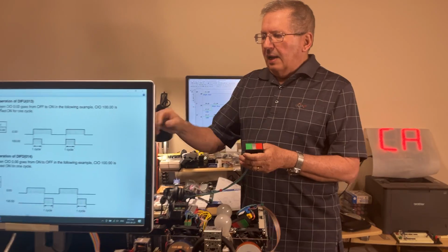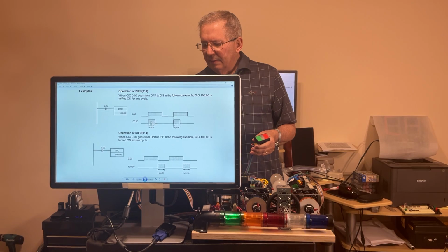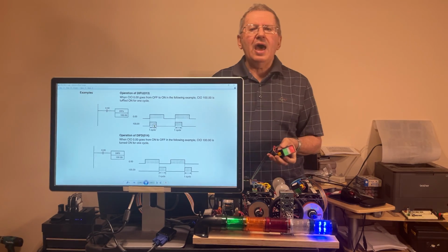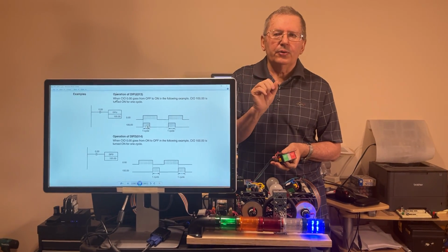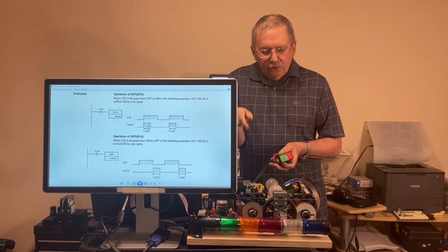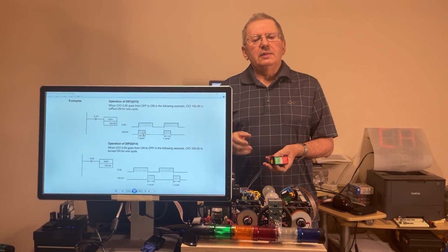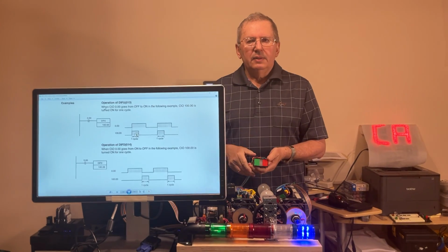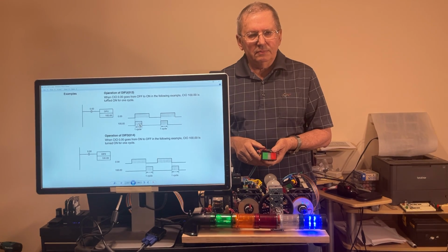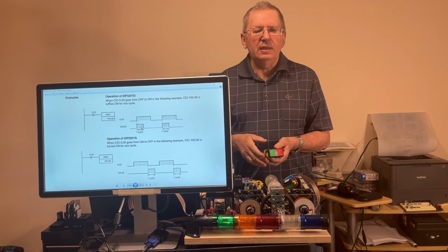It determines, exactly like you can see on the screen, a monostable, regardless of the duration I hold my finger on it. But this time I don't have direct control over the duration itself, because that particular instruction is related to the duration of an executing cycle for my PLC. As the executing cycle for my PLC is very short, the instructions are executed one by one, let's say in tens of microseconds. It doesn't take long. So the whole program, because it's a short one, is going to last maybe milliseconds.